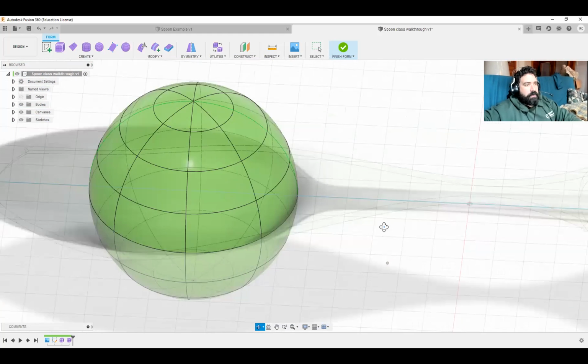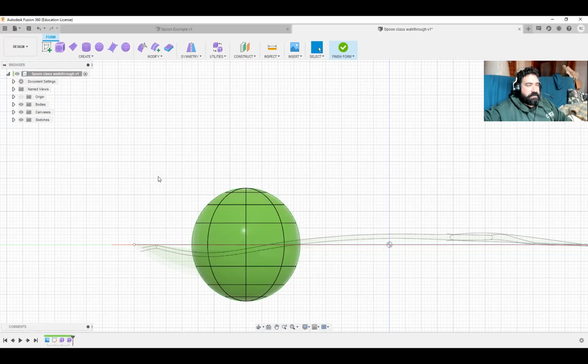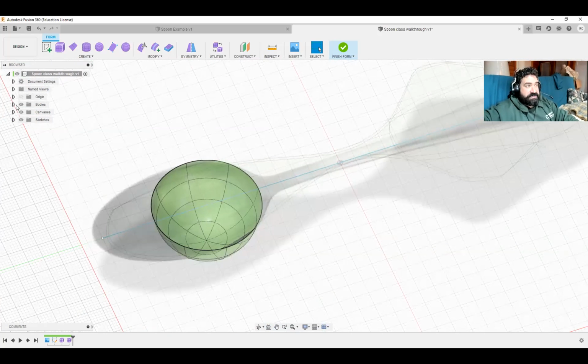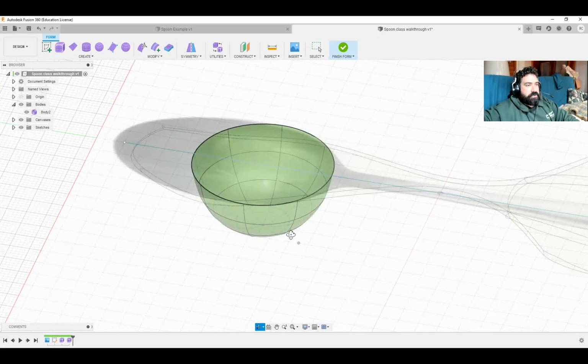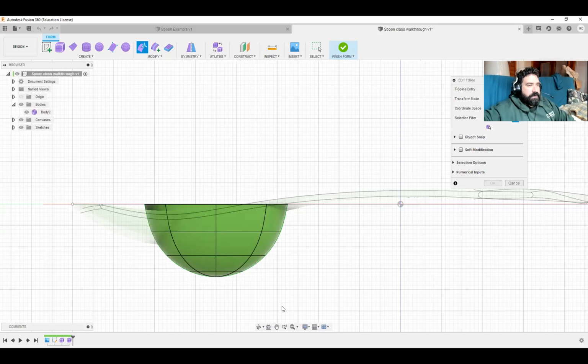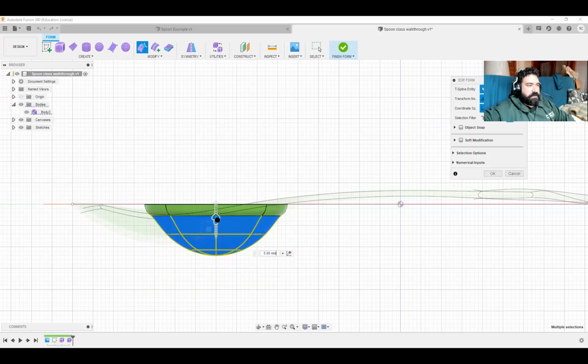Okay. Well, why would I start with a sphere? Because first, I'm going to chop the thing apart. Select up there, press delete. That chopped it in half. Now I have an open bowl form. It's just a bowl. Cool. Now I can start to edit that form, and I can play around with these faces. First, I'm going to shrink this down a little bit, meaning I want to compress the bowl a little bit. So select those, move it a little more shallow.